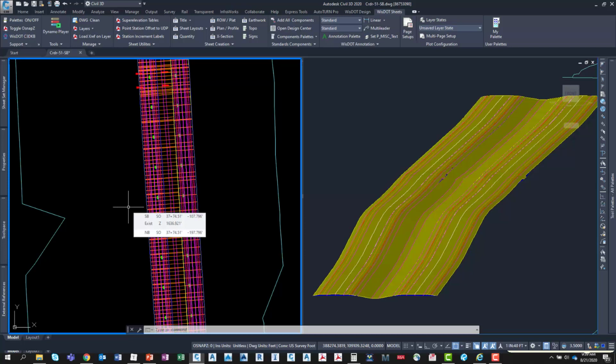Perhaps cul-de-sacs could use this workflow of extracting a feature line and using the relative feature line connections with the standard sites and feature line capabilities. Roundabouts are a possibility for extracting feature lines and using multiple corridors when modeling a roundabout. And then, as you see, a divided highway could work as well.